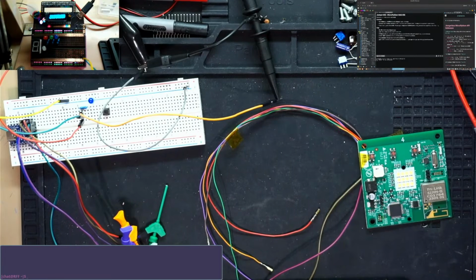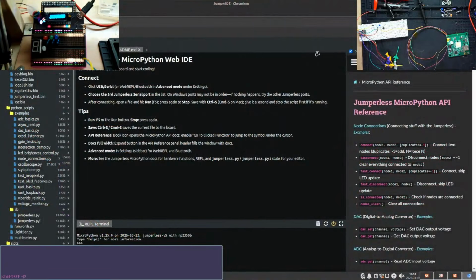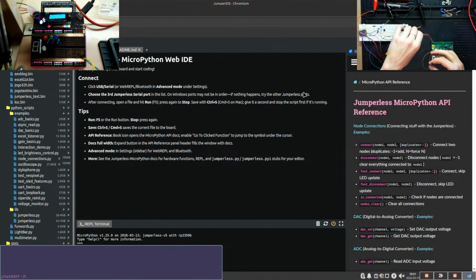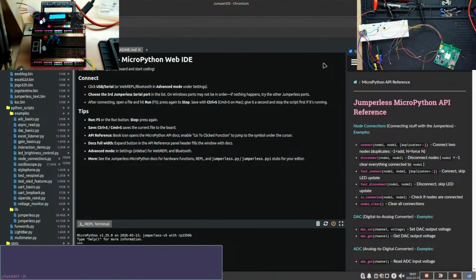Alright, so may want to make a new folder. Get the screen going over here. So I've already got a test board. I do want to test a couple of these pins. I think I had UART on this. I haven't messed with this board in a hot minute. But I've got some pins that I want to test and see if I can get UART on, and maybe that'll give us some good feedback for our fault injection tests.